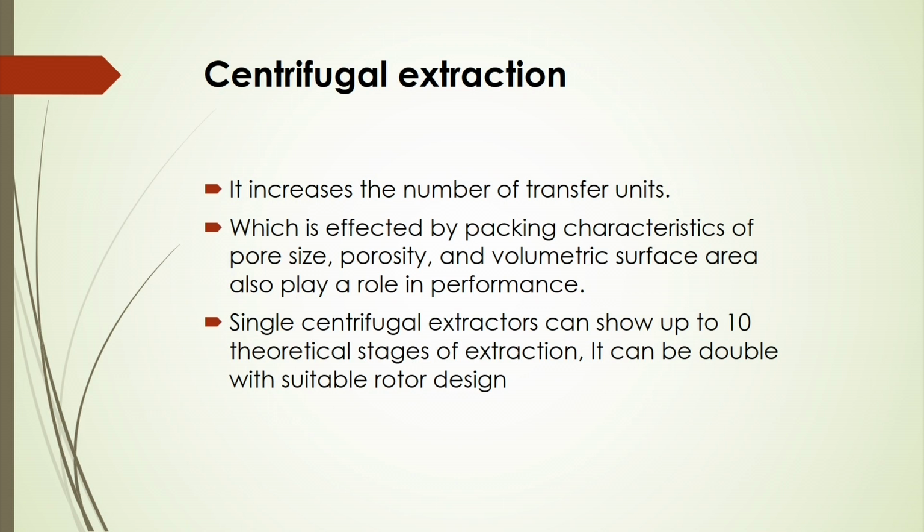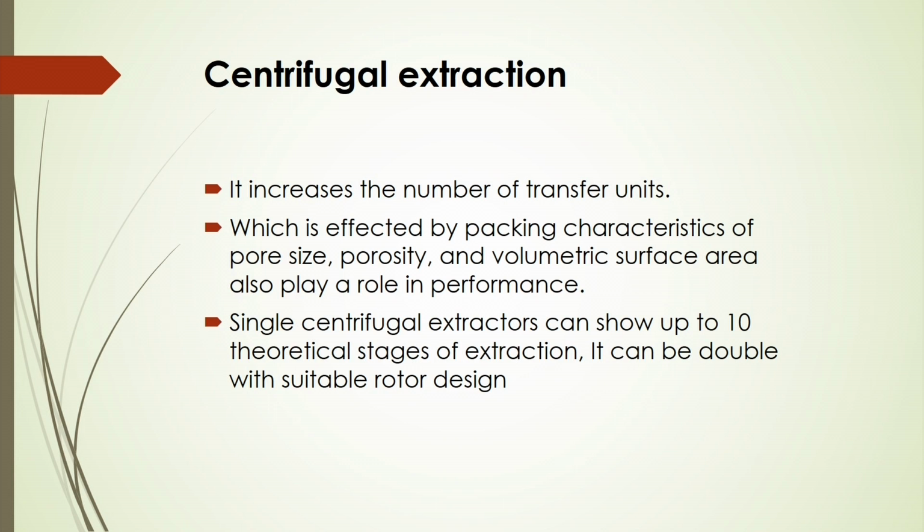Also it is affected by packing characteristics of pore size, porosity and volumetric surface area. Single centrifugal extractors can show up to 10 theoretical stages of extraction, and it may be doubled with suitable rotor design. So, if you suitably design the rotor, you can increase the extraction efficiency, and the efficiency can also be increased by suitably designing your packing characteristics like pore size, porosity, and if you can increase the volumetric surface area, that may also affect extraction performance.